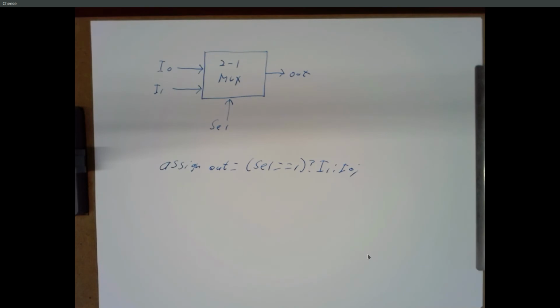So this starts moving us towards a theme, which is, even though you can do gate level design in Verilog, even though we can say give me a 2-input AND gate and a 2-input XOR and a 3-input OR and connect this to that and this to the other thing, the real power of Verilog is you can tell it what you want your circuit to do, and it'll figure out what the circuit should look like. As opposed to saying, here's what my circuit should look like. It should have 2 AND gates and a connection from here to there and so on. It's nice when you tell Verilog what you want your circuit to do, and let the software figure out how to make the circuit do that.